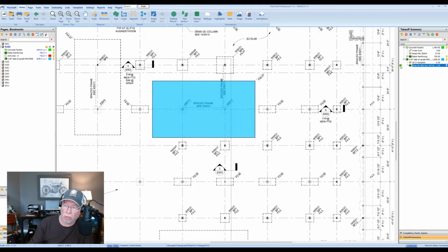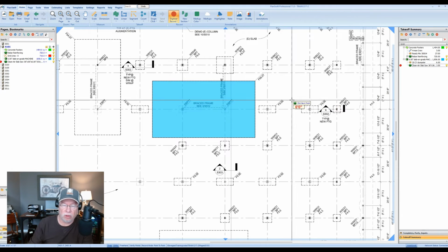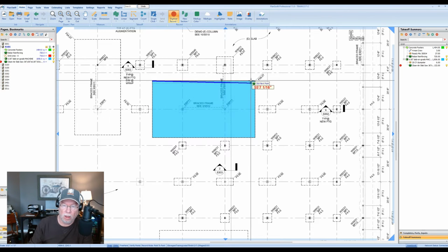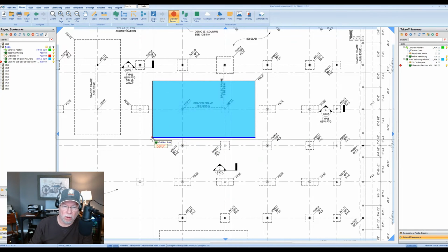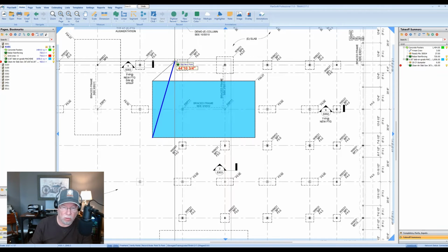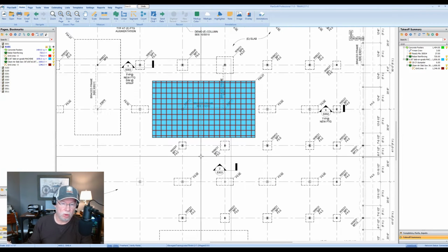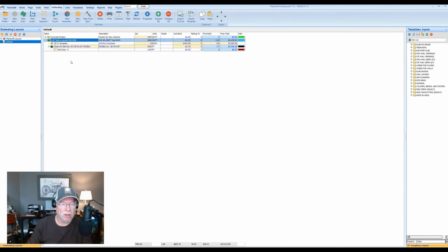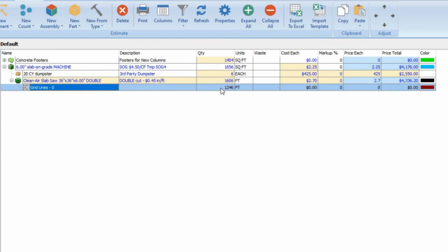And now I can start recording. Go back over to my item, hit that green, and now it turns to red. And I'm simply going to click in through the snap feature of the area I've already done, and then I could either hit this digitize record or hit escape. Either way ends the recording. And now the grid tool has provided me a grid, which is basically my cutting diagram. What I'm going to cut it into, and keep in mind, it simply divides up this rectangle into 3 by 3s.